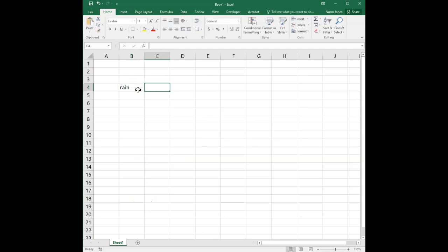And so I'm going to say rain. We have 20 inches per year. And infiltration is 0.15, 15%. So we'll mark that. And so our recharge will then be equal to 15% times 20 inches per year. So 3 inches per year. However, we need to convert that into feet per day. And so we have to get it in the right units.